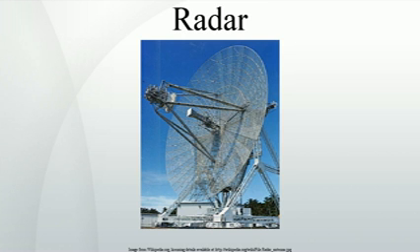Clutter is detected and neutralized in several ways. Clutter tends to appear static between radar scans. On subsequent scan echoes, desirable targets will appear to move, and all stationary echoes can be eliminated. Clutter can be reduced by using horizontal polarization, while rain is reduced with circular polarization.